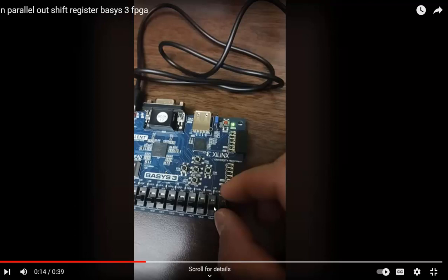If you don't do that and just use the default value when you declare it, it's going to be 0 by default. So you need to use 3 as a count max instead of 4. When the counter equals 3, then you do something, instead of 4, because it starts with 0. So it's going to be 0, 1, 2, 3, so 4 cycles.